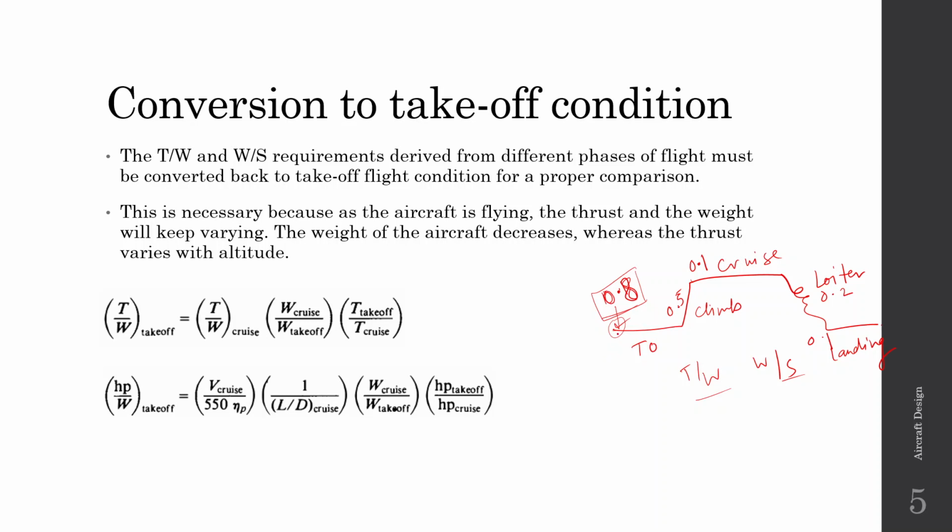The issue is that when the aircraft is flying, the weight of the aircraft will go down, and also since the aircraft is going to higher altitudes and then coming down to lower altitudes, the thrust produced by the engine will change. This approximately varies with rho at the altitude by rho at sea level, into the sea level thrust.